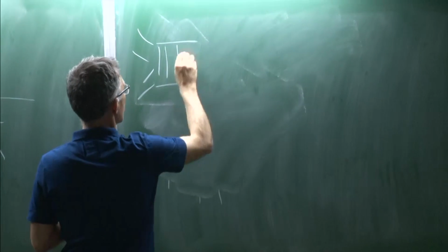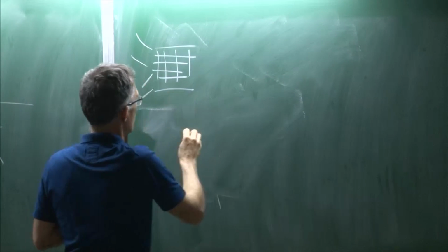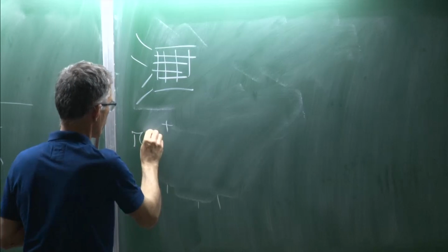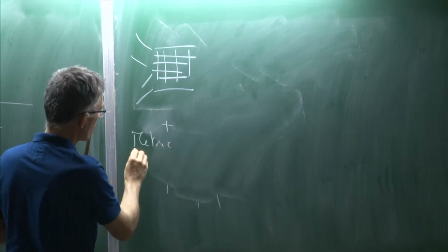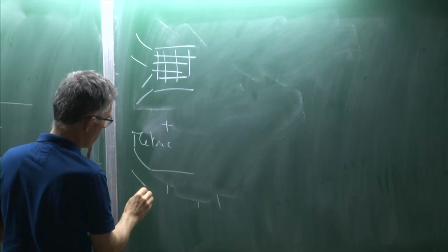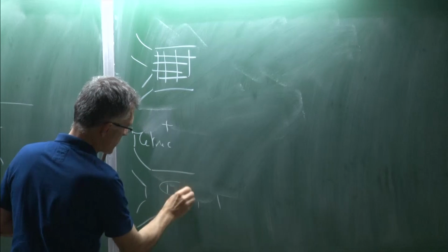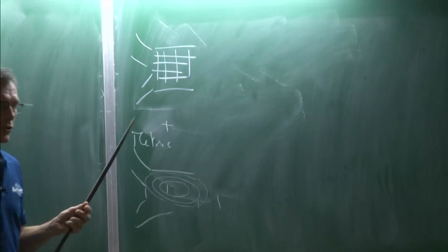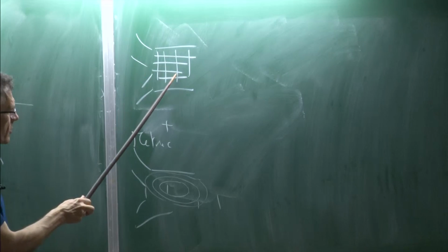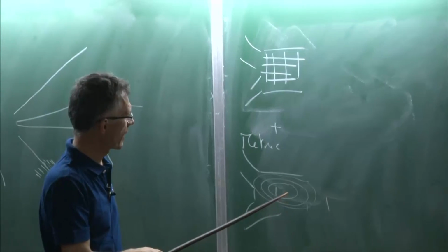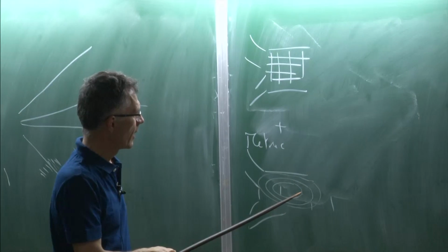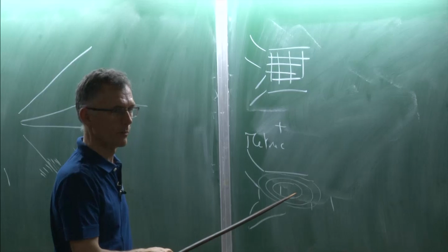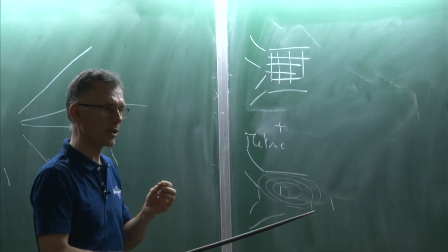You take the mesh, and you add a metric. And the metric is usually a 3D field on the same flow, which has gradients, etc. And MMG3D, this code will look at this mesh, look at this flow field and tell you, okay, you have big gradients here. I'm going to move the mesh to be better here. And it's moving the mesh according to the metric.